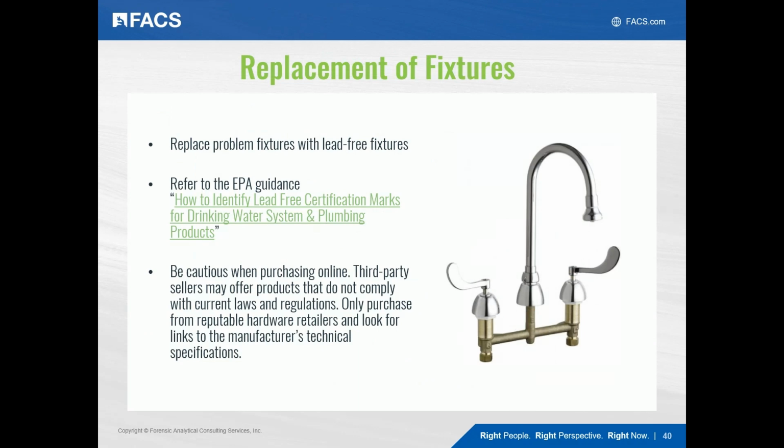Replacement of fixtures. Make sure that the new fixtures are lead-free. So the EPA has guidance on how to identify lead-free plumbing fixtures. Just be aware that the term lead-free actually doesn't mean 100% lead-free. It just means that it's below a certain allowable percentage of lead. A very small amount of lead is allowed to be in fixtures.